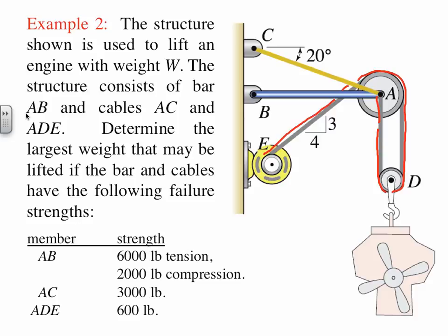You may be tempted to substitute one of the given failure strengths in for the load carried by an element, but we don't know which structural element reaches its failure criterion first, and they won't all reach their failure loads at the same time. For now, we'll label the engine block weight as W and treat that as known.